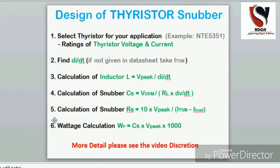Next is the design of the thyristor snubber. There are basically 6 steps required. The first one is selecting the thyristor application, and you can find out the voltage and current rating from the data sheet. For example, I have taken the NTE5351 SCR, and the data sheet is available on Google also. If you want the data sheet, you can find the link in the video description. Second is to find out the di/dt. It is also given in the data sheet only.